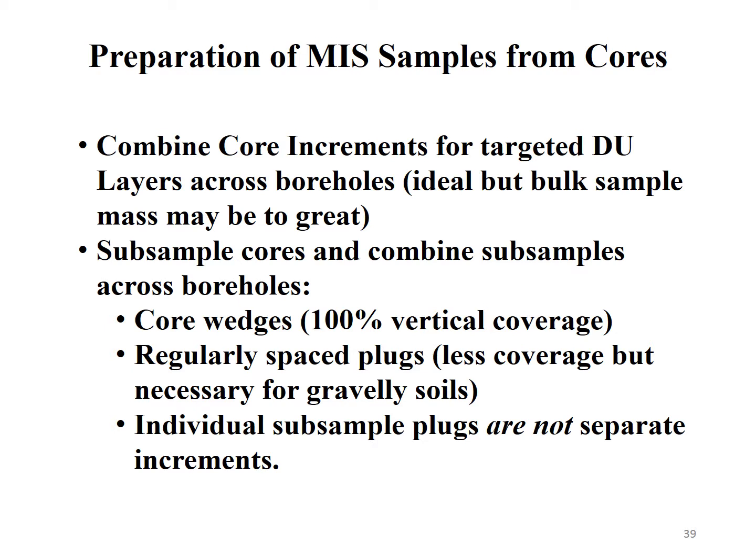When coordinating VOC sampling, it is also critical to ensure that you work closely with the driller so each core brought to the surface can be opened and subsampled by the sampling team in as short a time as possible. Again, we're trying to minimize potential loss of VOC, so you want those cores processed as soon as they're brought to the surface and opened up.